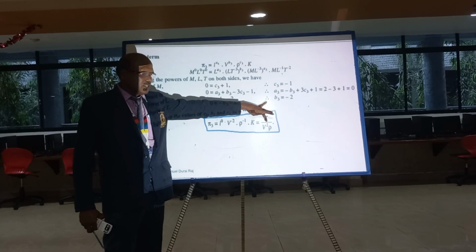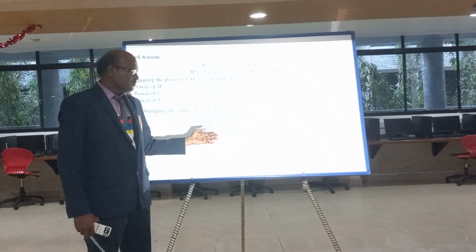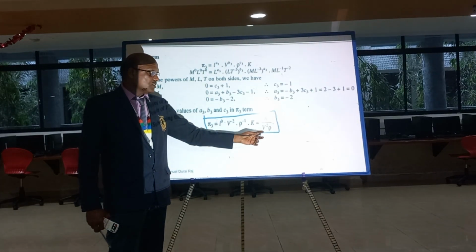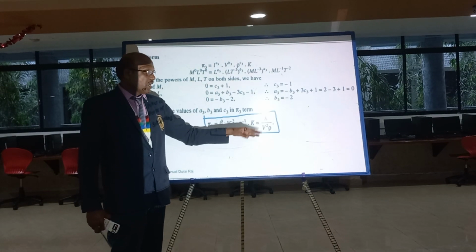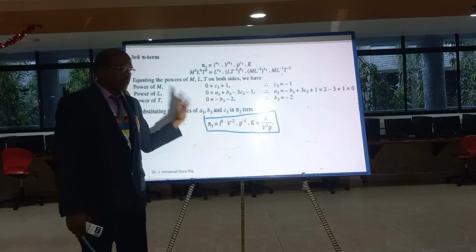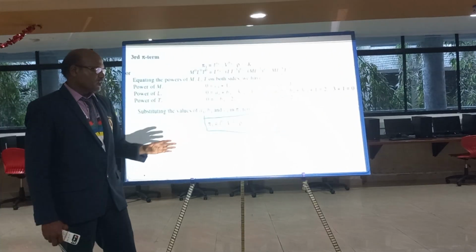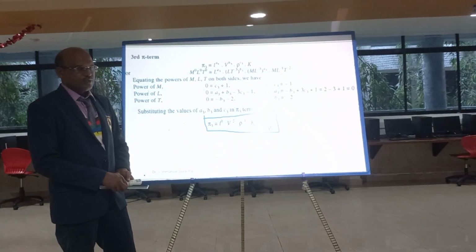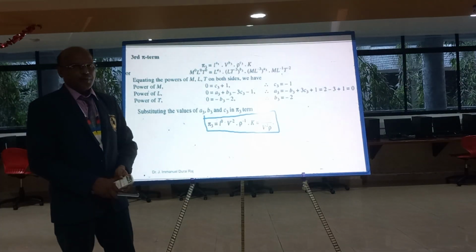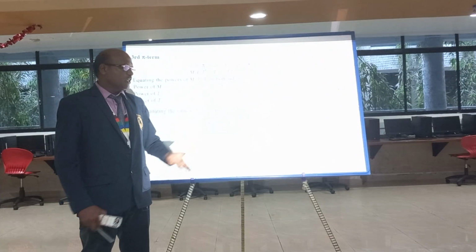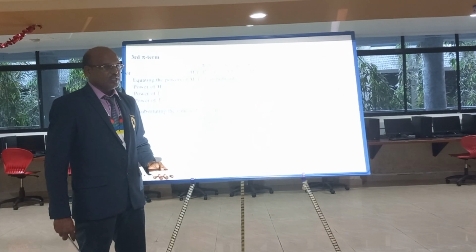The bulk modulus is not affected by length. It is a relation having velocity and density, not directly related to L, so L goes to 0. So I can find a relation between the parameters L, V, K like this. Once you find phi 1, phi 2, phi 3, you go with the first equation and write.